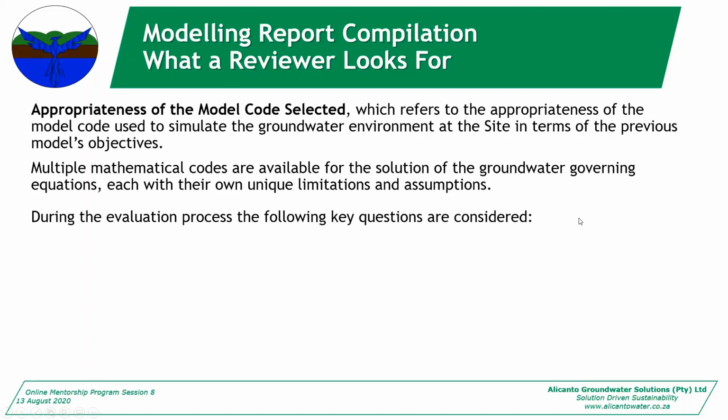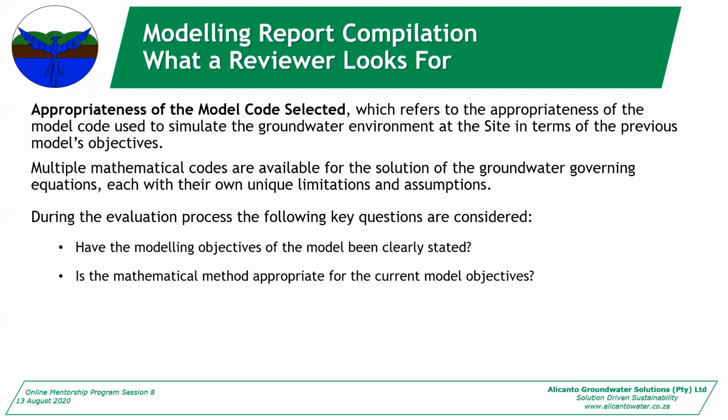When you're evaluating, the key questions you consider are: have you stated your modeling objectives? Have you said this model is used for environmental impact assessment or dewatering strategy design? Is that in your document? Is the method appropriate for the current modeling objectives? If you've chosen an analytical solution that is applicable only to unconfined sandy aquifers, meanwhile you're applying it to a granitic aquifer that's confined, then it's not applicable.